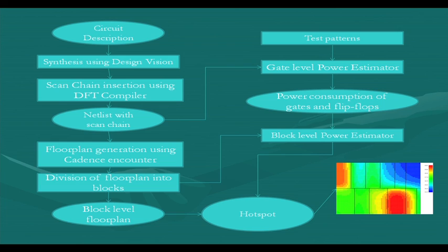So, the steps are much more complex, and in particular at the lowest level, to get the temperature values, we have to go for a thermal estimation, which is time consuming, and there is no such straightforward guideline like more scan chain transitions meaning more temperature. There is no such guideline. Scan chain transitions being more, the circuit power will be more, but how the individual blocks within a circuit consume power, their consumption pattern will change. So, it is not depicted by the scan chains. Naturally, the procedures that we have to use are to be more elaborate and more exhaustive in nature.